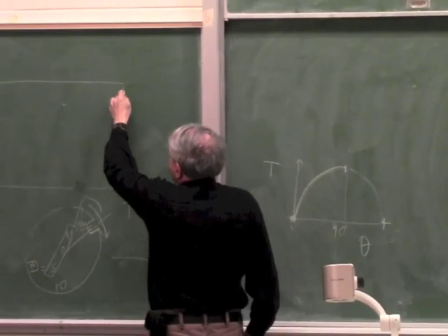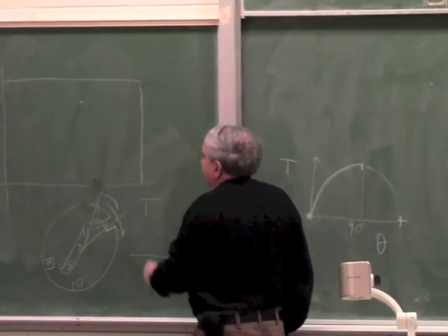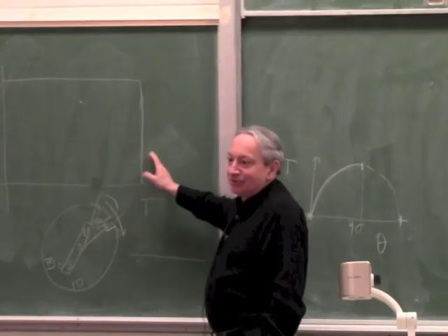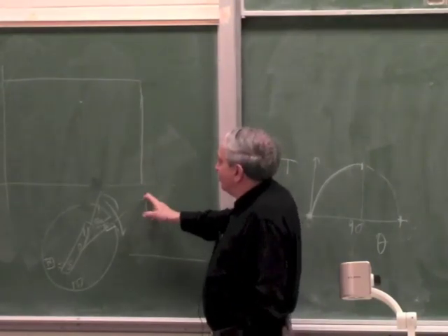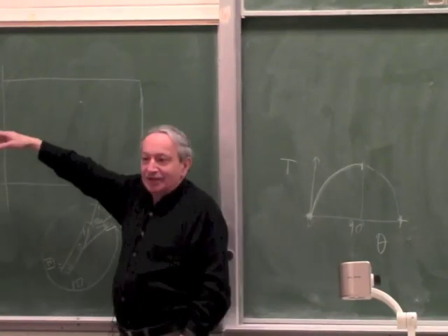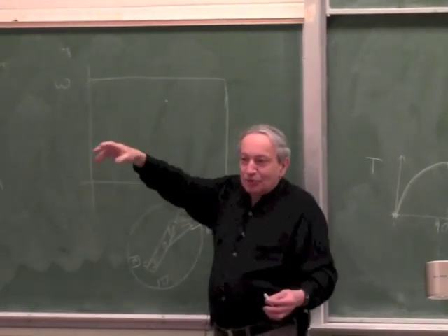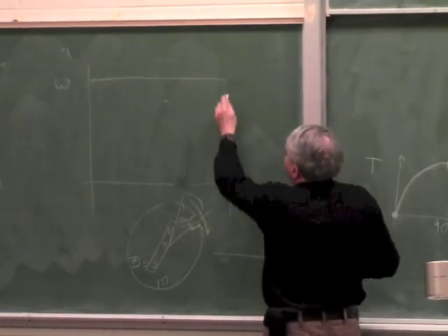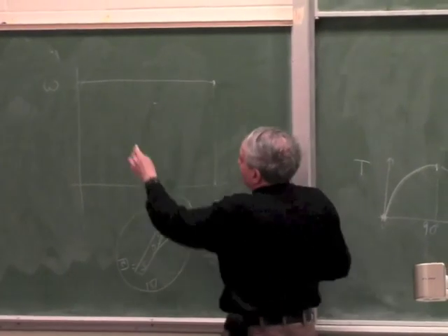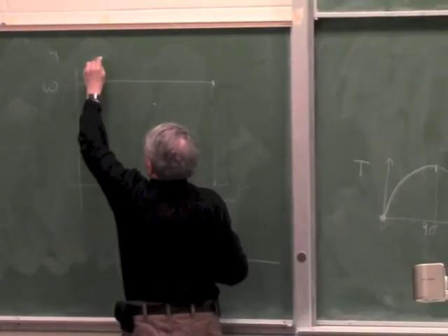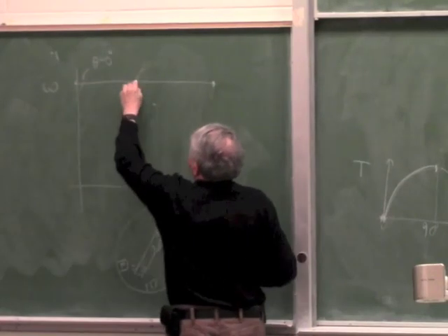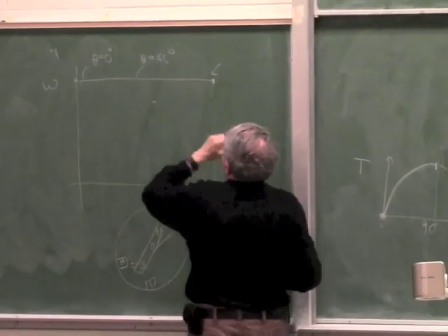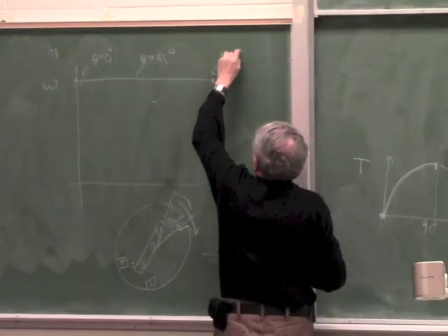The line doesn't really look like this, because if there was really a solid line here, it would imply that you can use a motor as a constant torque motor. See, this line implies that torque is constant and you can change the omega. Okay, there are such motors which are used as constant torque, but that's not really what happens. What happens, it collapses. If you reach this point, the power angle theta is 0 here, because there's no torque.